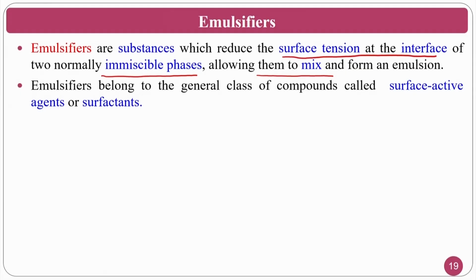called an emulsifier. I have mineral oil, I have water, and if mixed, it is not proper. In those circumstances, emulsifiers are used. Whenever you get a cutting fluid from the market, for example, the Servo companies supply Servocut S, whenever you mix it into the water, automatically it mixes. You don't require any emulsifiers, because it is already inbuilt in it. Whenever you use it, it will mix properly. That is why you will always see a white, milk-type color.